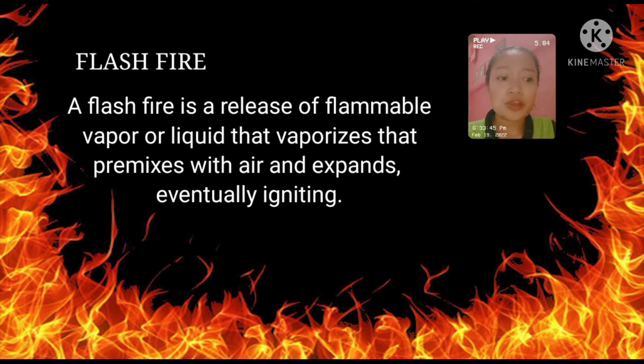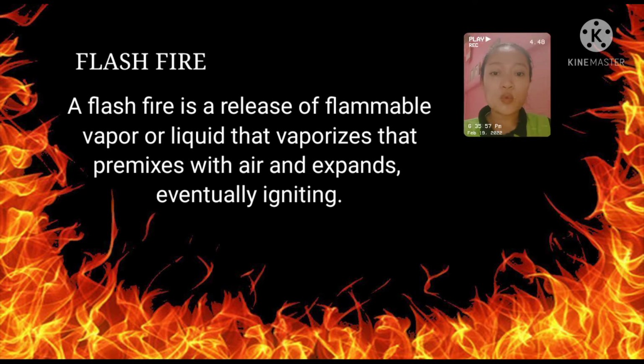A flash fire is also a release of flammable vapor or liquid that vaporizes, mixes with air, and expands, eventually igniting. Once ignition occurs, the burning velocity travels from the point of ignition toward the release point, potentially igniting the source as well since it ignites the entire volume of the vapor mixture.